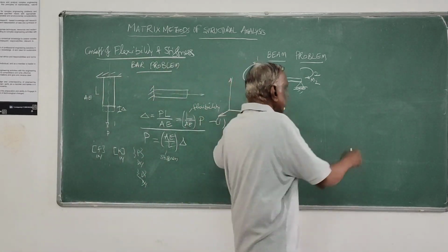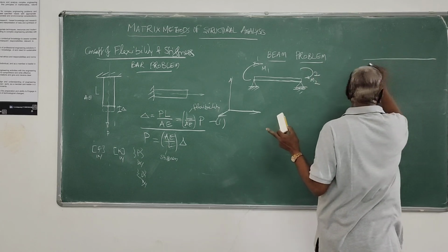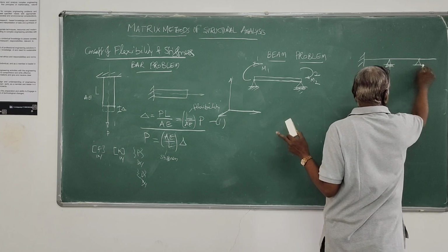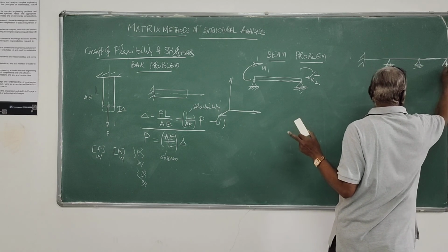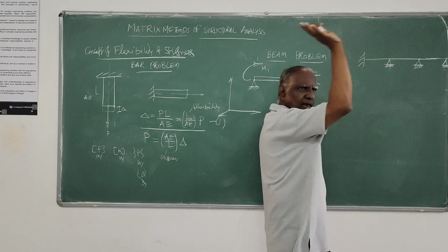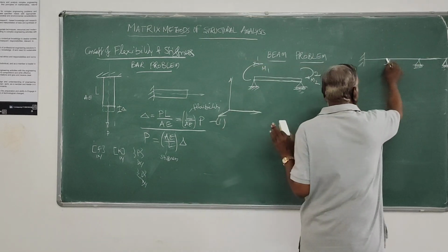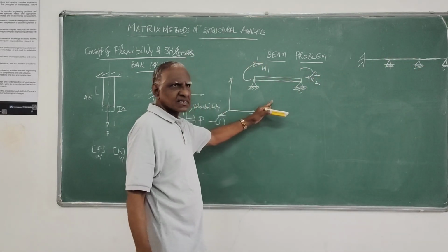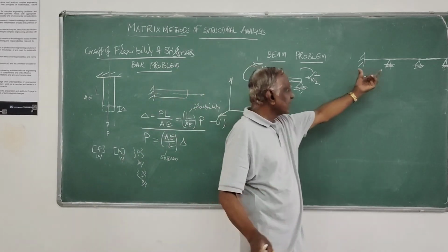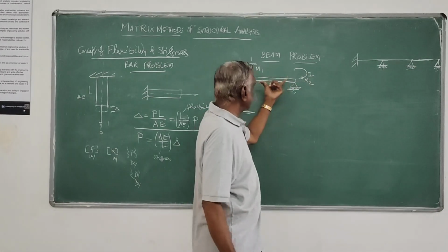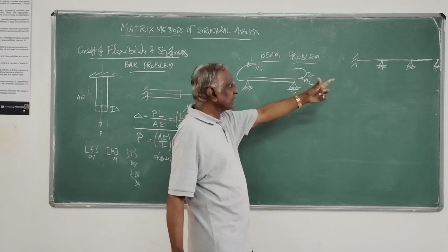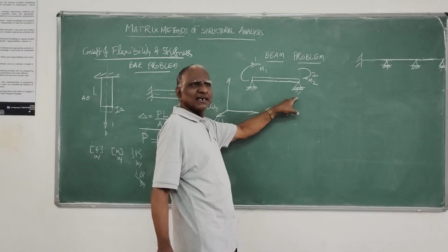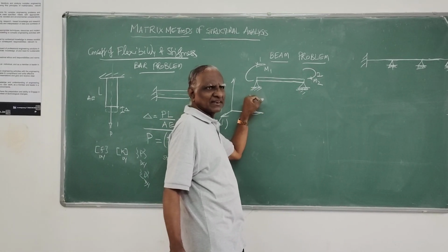So this particular example what I am considering is from a practical beam example. Suppose if you take a continuous beam in practice having infinite length, I will consider only this intermediate beam to define what is stiffness and flexibility. This intermediate beam will be like this, which has supports. Always here I cannot take both roller, it will be unstable. I will represent it hinge.